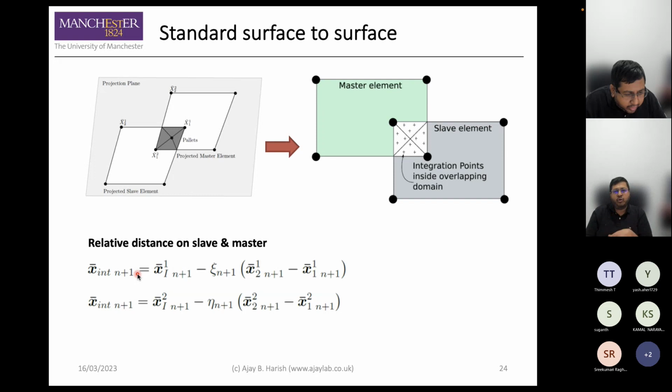And the second thing is, if your mesh densities across the two surfaces are different, then surface to surface strategies fail. Right? So there's, to some extent, a bit of tweaking to find the right recipe in